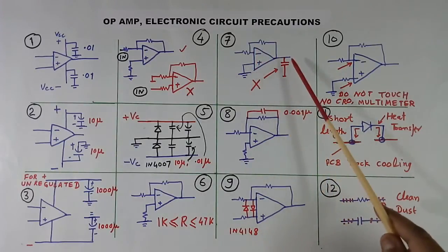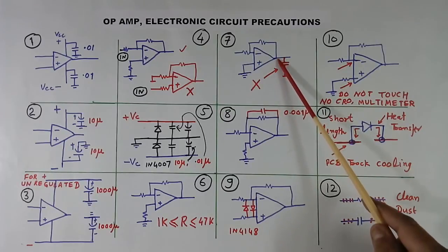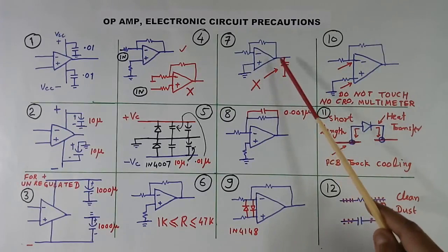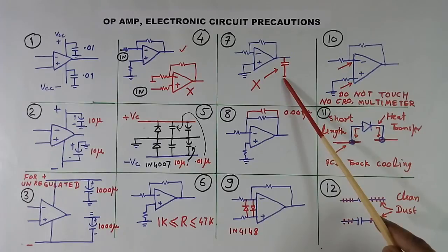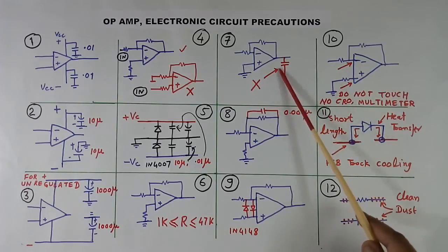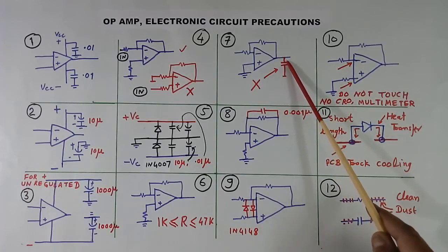Then even though many ICs have output short circuit protection, we should not drive a capacitor directly. This should be avoided. You have to put some resistor.